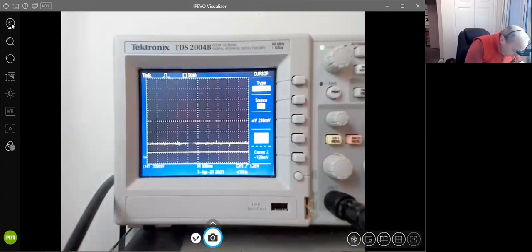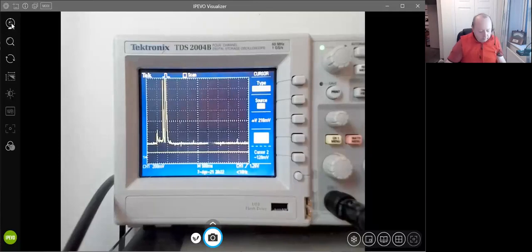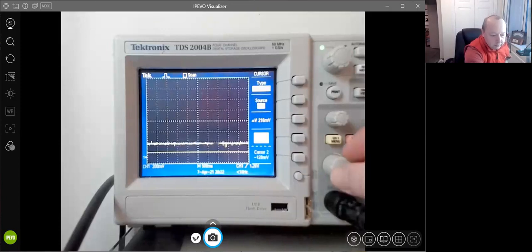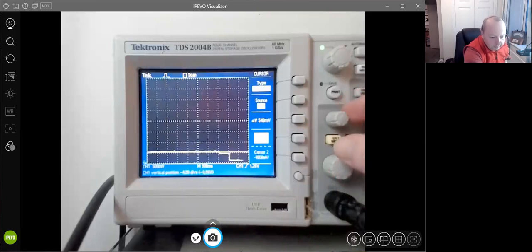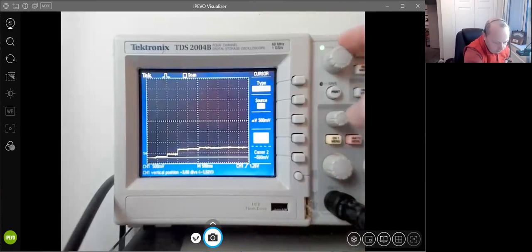The other thing I can tell you about piezo sensors is they are polarized. So if you do fit them the wrong way around, as I discovered, they tend not to work. Right, there we go, that's working. A wire just came out, so I just had to put it back. So you can see our time base there at the bottom.